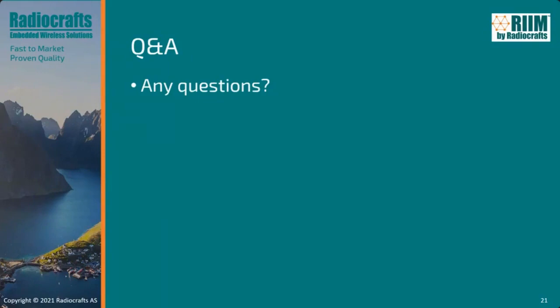And the Q&A on antennas. I think we have an application note on antennas, but antennas are not black and white. It's always shades of gray, because it's always a trade-off between design, practical use of the product, and range, of course. We normally recommend the best solution, which is to have external antennas, either dipole or monopole. But in many cases, customers choose otherwise because of design reasons.